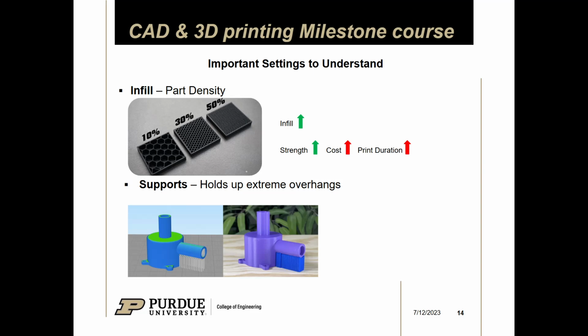Unfortunately, 3D printers are subject to the laws of gravity and stuff like that. So if you try to print this, as the nozzle is extruding it, the filament would droop because it comes out molten and soft. It'll droop as it comes out, and then your print will fail and it'll be really sad. So one of the things you can do to mitigate this is by adding sacrificial material that you will print underneath your model. It'll print over it, and then when you're finished, you break it off. Right? So that's what a support is. It's just a sacrificial material.